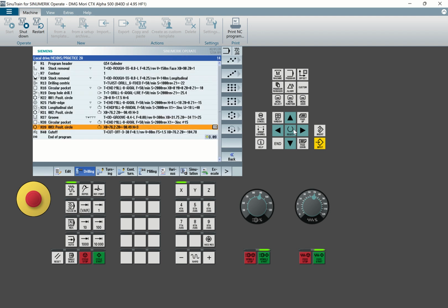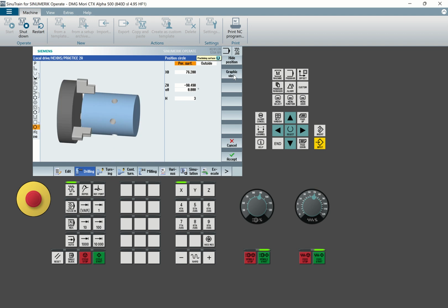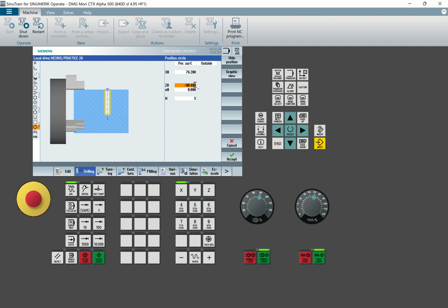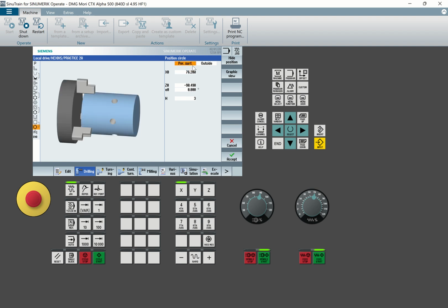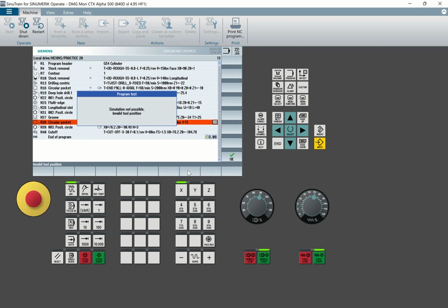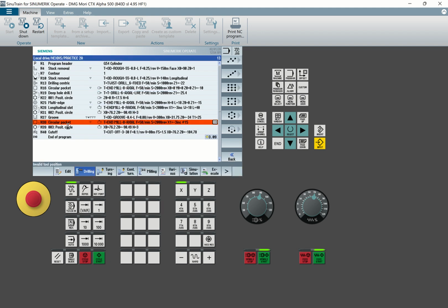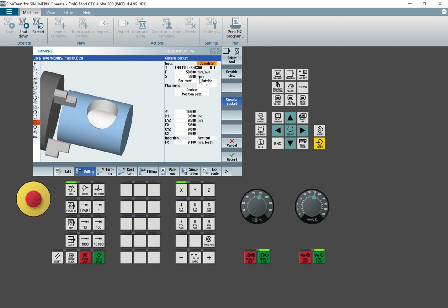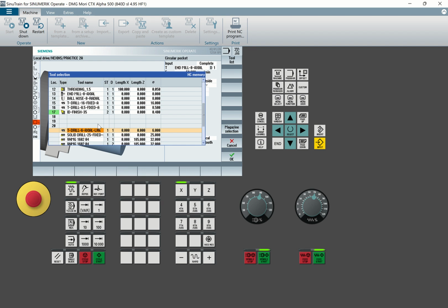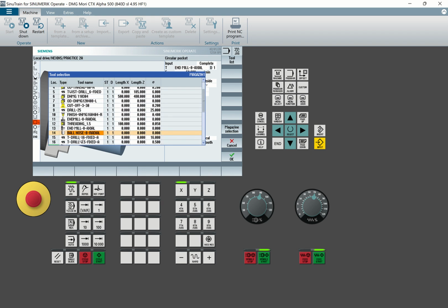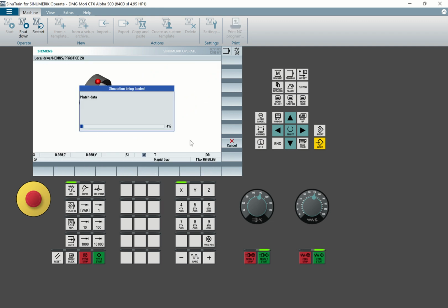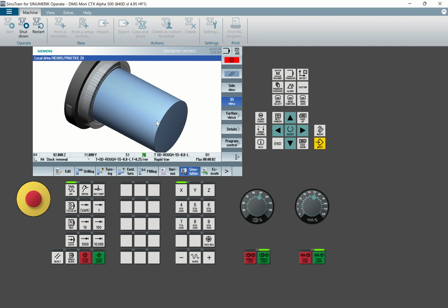Okay, let me check this one, graphic. I want to put 3 of it at this point, diameter 76. So also face C. Okay, let me check these parameters. I think it's the tool, yeah, the tool, and the mill should be radial, not axial. I want to use end mill radial, 8, accept, then do simulation. Not axial, because axial is on the face C, so it should be end mill radial.